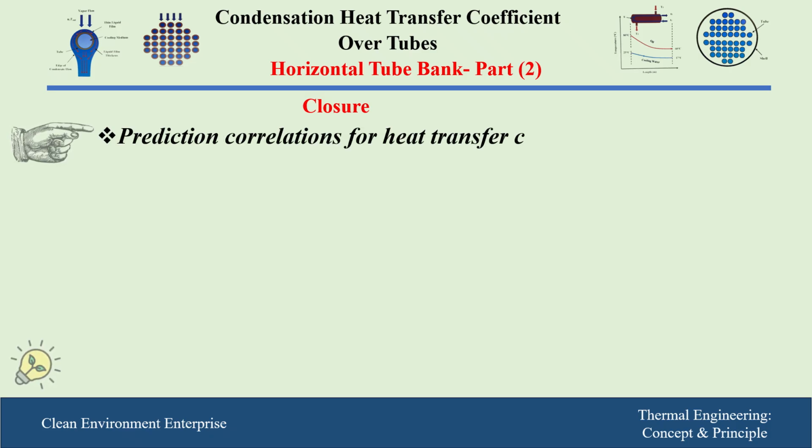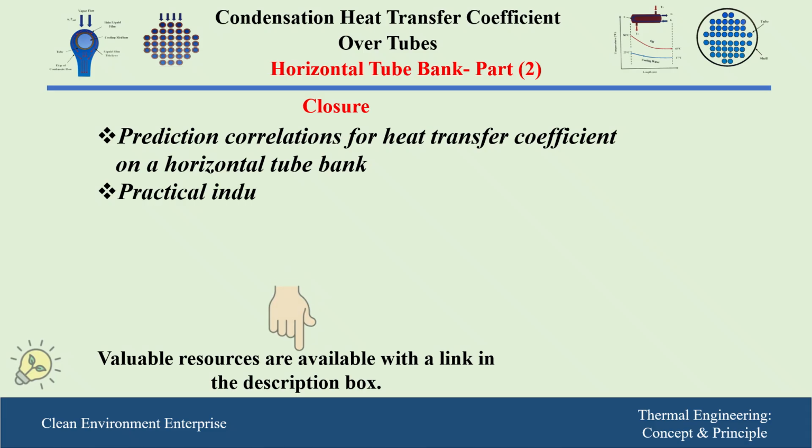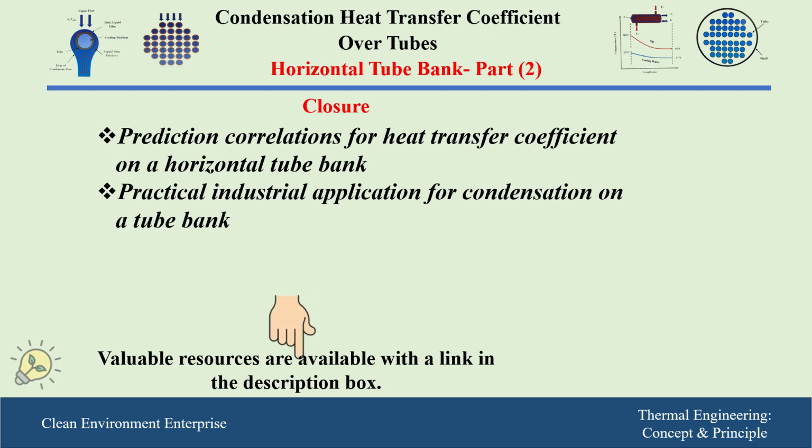We talked about the available correlations to predict the heat transfer coefficient for the condensation process over a horizontal tube bank, and the practical case study for the condensation of vapor in a condenser, which is used as a part of an organic Rankine cycle. And we predicted the overall heat transfer coefficient by different correlations.